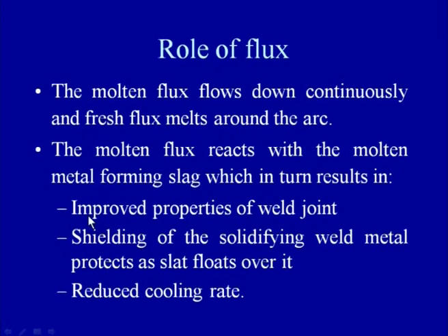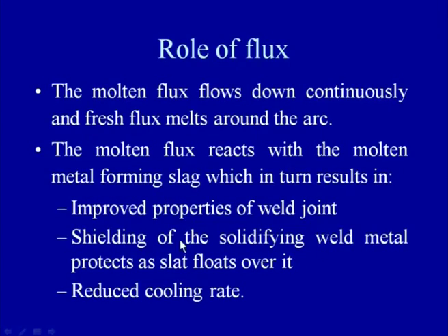Because of the reaction of the molten flux with the impurities present in the weld metal, these impurities are taken off or removed by the flux, which in turn helps in improving the properties of the weld joint, and it provides the shielding of the solidifying weld metal to protect it from the atmospheric gases.